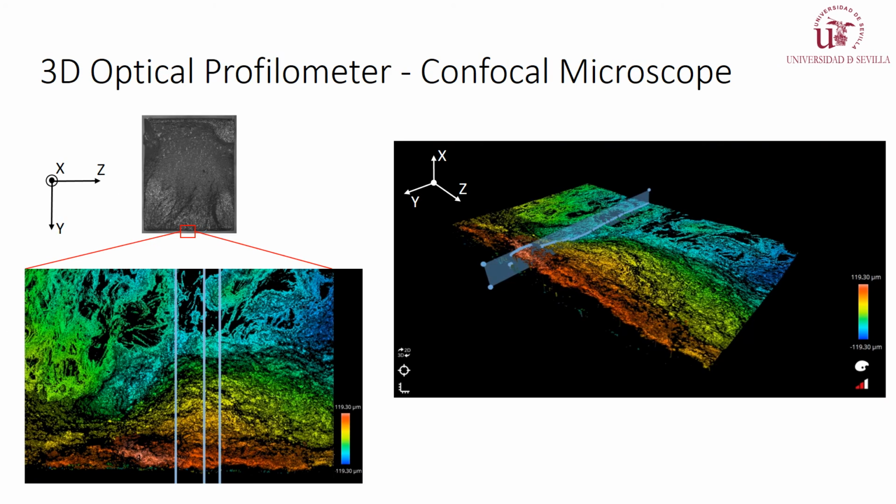The initiation crack angles are measured with a confocal microscope to obtain three-dimensional maps of the cracks that caused the test specimen to break. An example of this is shown in the image, where the measured area is 0.4 mm by 0.24 mm. On the left, there is the same three-dimensional map with three parallel intersections in blue, which will be seen on the next slide for the three test specimens. These intersections in blue represent the profiles of the crack at different points. These cut planes will be around points where the cracks possibly initiate.